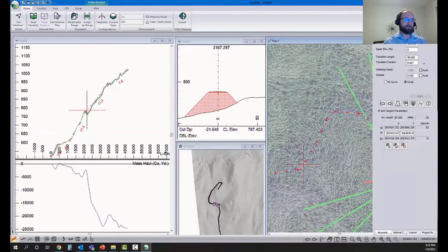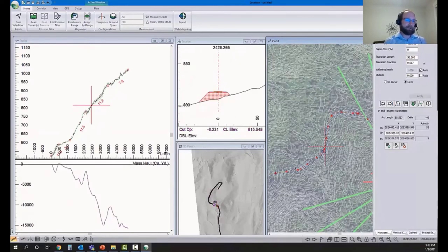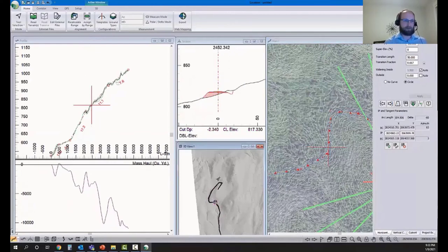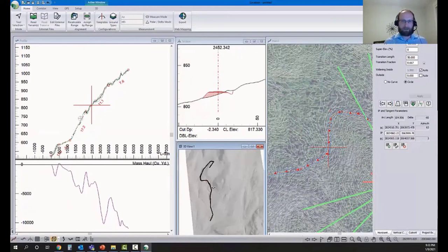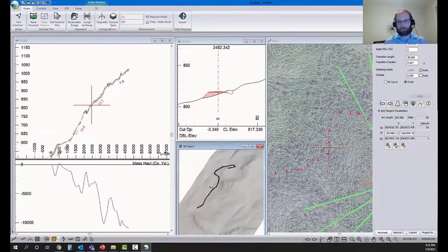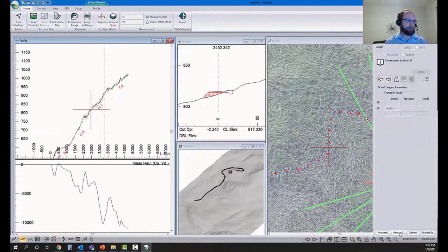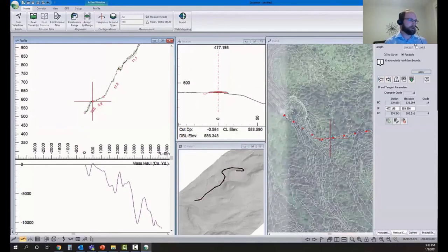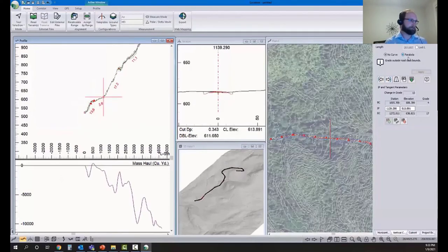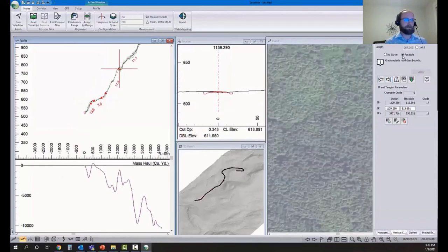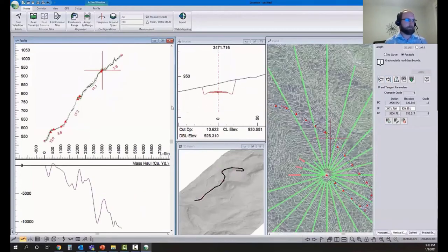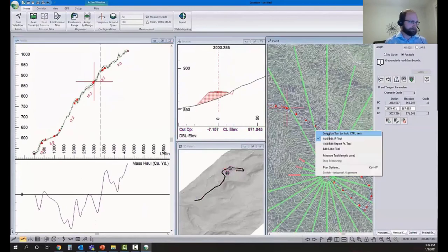Oh, one thing that I missed while the video was playing is I've added in curves. So if you're designing a low volume, low speed in-block road, you can use a tight curve appropriately, whereas if you're designing mainline infrastructure, you can up your design speed, use appropriate curves for that, and keep things safe for your road users. Just applying vertical curves, and same thing, just a matter of keeping things safe and comfortable to drive on.